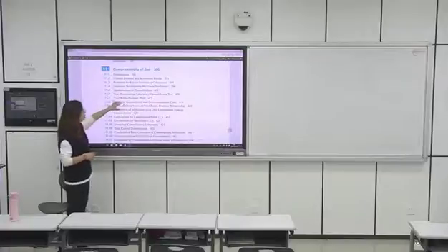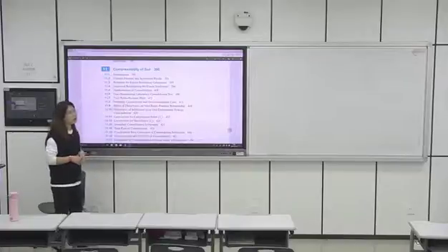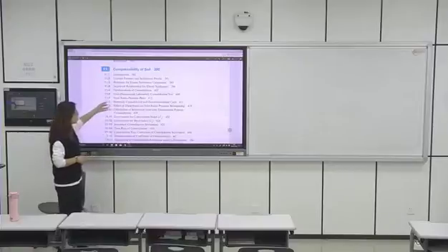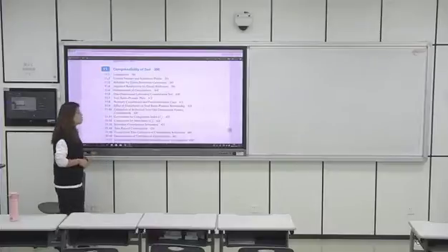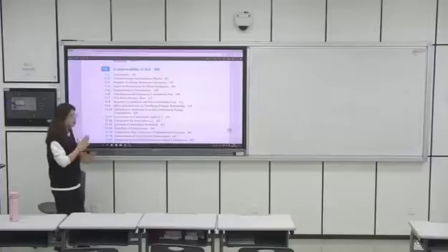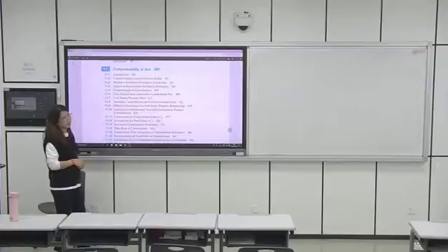How to get these plots? And after we got these plots, we need to define the pre-consolidation pressure, right? And the slope of the curve. That is the compressibility index.